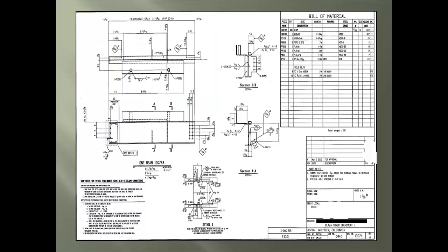Moving to other important detail cuts within the sheet, we see this detail number 1 callout, and here is the location of that detail. Next, we see this section cut symbol, like we've seen on the column sheet, and here is where we find the detail. Now notice how right next to the first section cut view we find another section cut view with the detail being found up here.